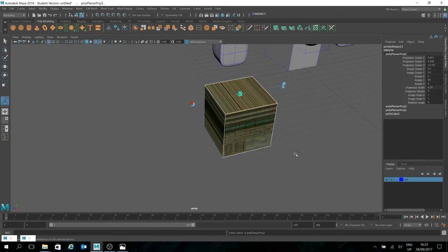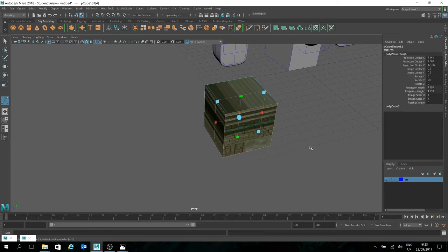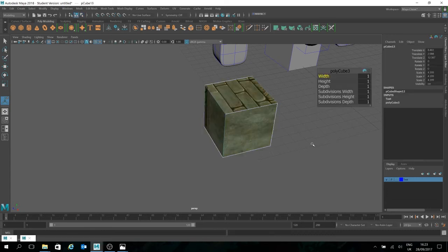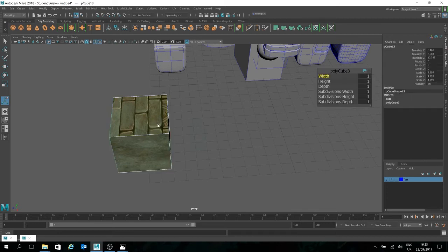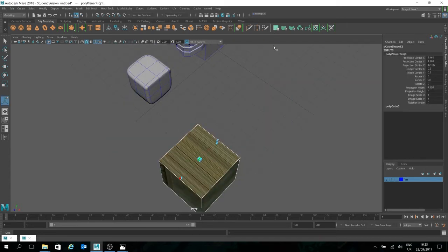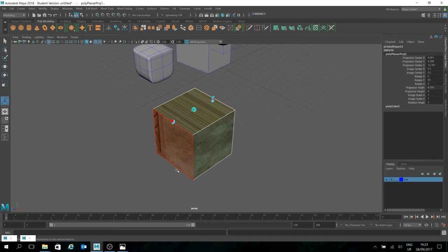So now, I'm going to click on this. Okay. I'm just going to pick a face and I can do a projection mapping like that. But it will not give me the proper projection. Why? Because the projection is now on the y-axis. You have to change the axis. This is flat now, super flat. You have to make it 0 and then rotate the x-axis or y-axis.